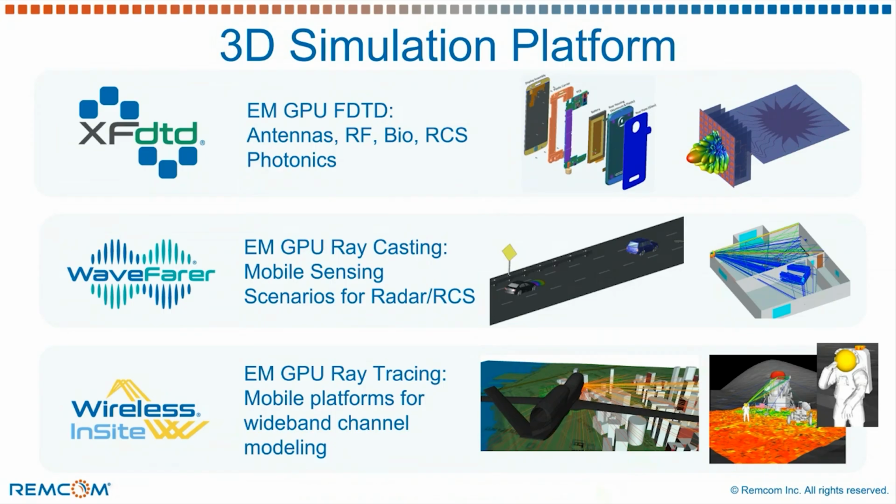So we have enabled users to model FMCW waveforms inside Wayfarer using physical optics, where we illuminate and target a access point and provide the backscatter from a target inside an environment. So this is a see-through wall radar use case where there is a person behind the wall, and this radar is able to get the multipath correct all the way to the target, the scattering from the target, and the multipath back from that target to the receive radar, to the receive antenna of the radar.